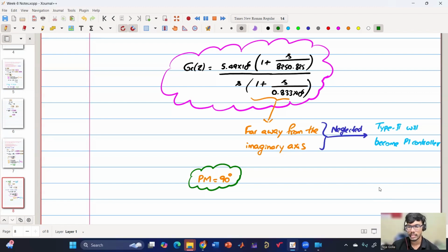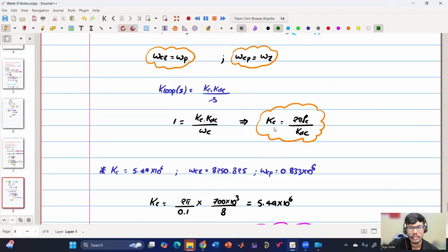So the DC gain is basically coming from the bandwidth. If we go to this equation, the gain of the controller is proportional to the bandwidth. Say theoretically it is possible to get a certain bandwidth, but practically there can be many other dynamics and many other issues, not covered in this course, that may put a limitation on the gain of the controller that can be implemented.